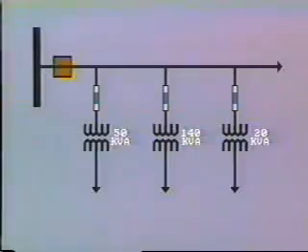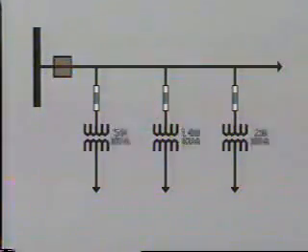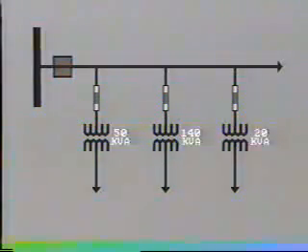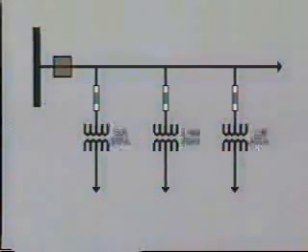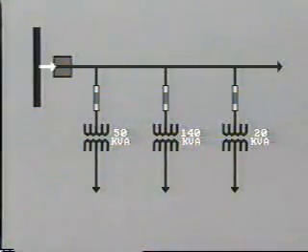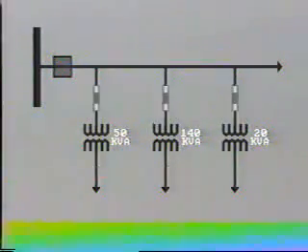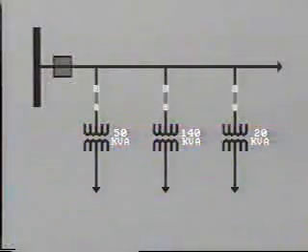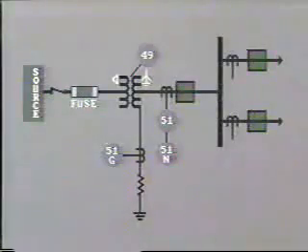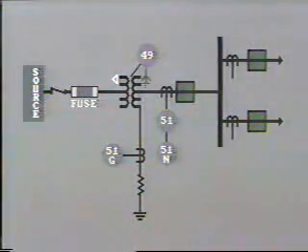On smaller transformers, it is usual to omit the primary side breaker for economic reasons. Typically, we may have many large and small distribution transformers tapping off a distribution feeder. The feeder will be fed from the substation bus through a breaker, but each distribution transformer will be protected by high voltage fuses only. Here is a typical protection arrangement for a distribution transformer feeding a small industry. Once again, the primary is delta connected and the secondary Y grounded.